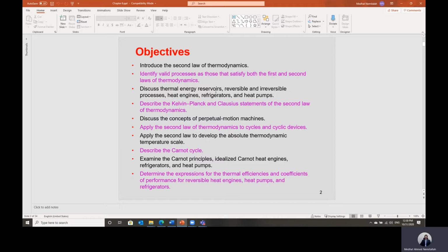Like in winter, you can just flip the air conditioning unit to have the condenser inside. Then it will absorb heat from the surrounding air outside your house and reject this heat inside your house. In this case, the air conditioning system works as a heater, or what we call a heat pump. Anyway, inshallah, we'll be talking about those differences later on.